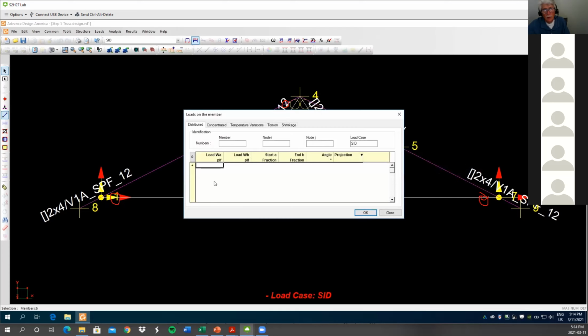Properties. So now you're gonna have to go and change this. Right click on the loads and change it to kilonewtons per meter. Right click, change units, kilonewtons per meter. Now, do you remember what the value is? Minus 0.12, correct? I think so. Okay, so minus 0.12. And that's it.